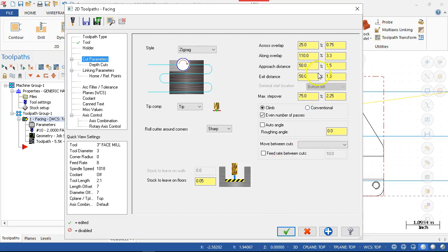All right, if I made this smaller, if this was 0, I could still be turning on this edge and it could lift off, but I would have a swirl mark there where the tool stopped. Possibly drug a couple more chips around with it, did a little washing machine at the bottom, and then did retract. That affects my finish. If I need the cycle time and I can stand to have that little bit of mismatch because we're going to have some other finish operation and it's not going to be as critical, we need a nice smooth clean surface, but it doesn't have to be mirror finish, I can get away with some of those time saving items.